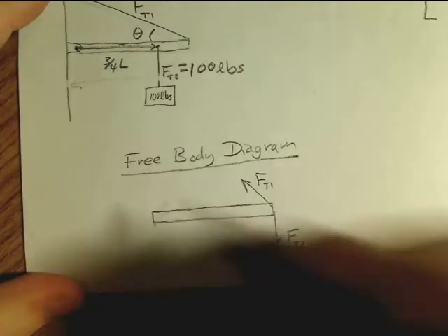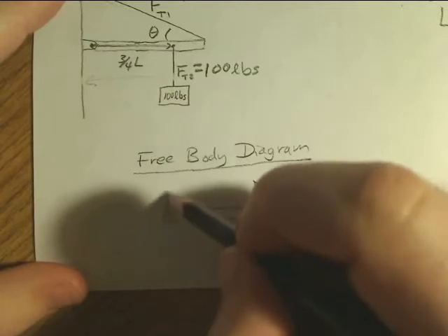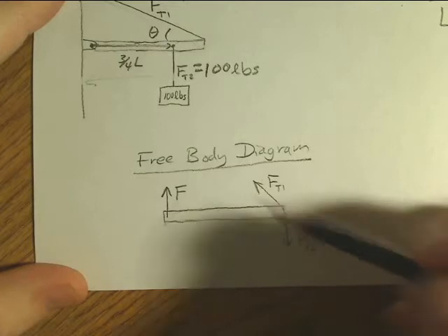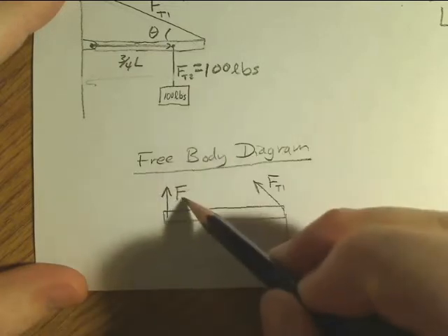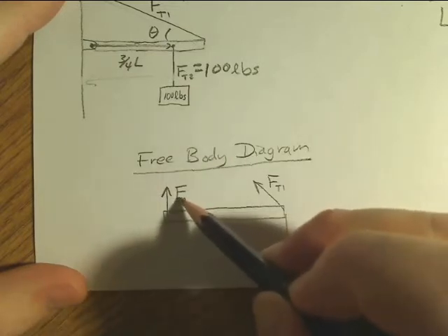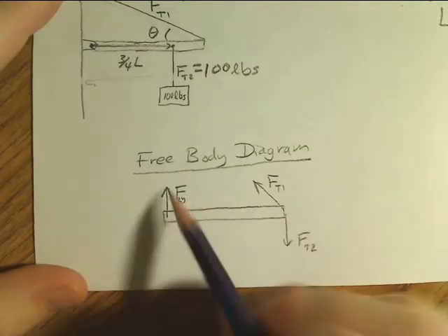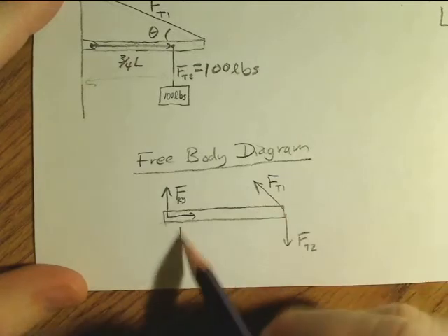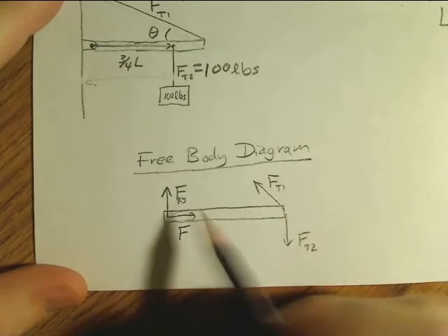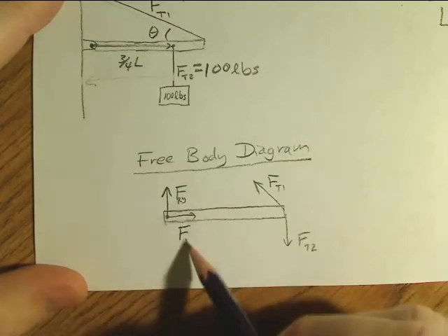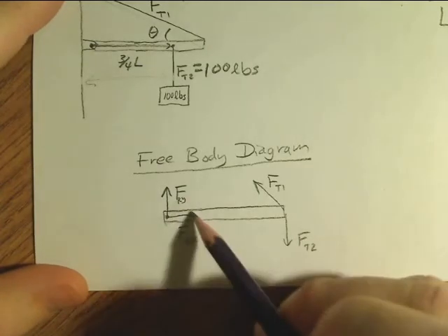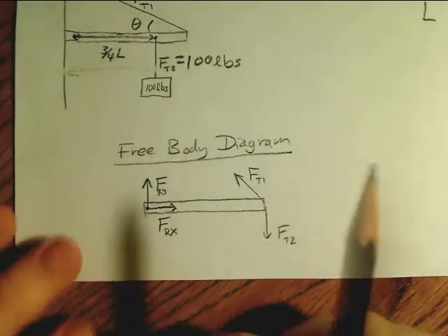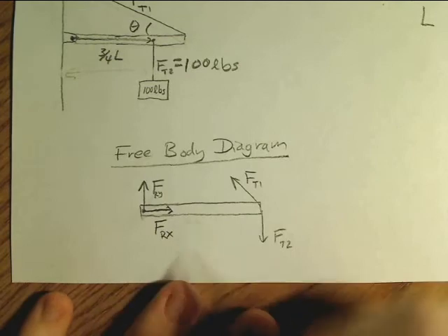Ft2. The hinge support has a reaction that's upward. It could also be down, but it's basically trying to support this, so I'm going to assume that it's going to be upward. We're going to call that RY, reaction in the Y direction. This cable is pulling back to the left, so the reaction force on this hinge support is probably to the right, like that. So those are the 4 forces acting on that. That's everything that's touching it, and we're saying neglect the effects of the gravitational pull.